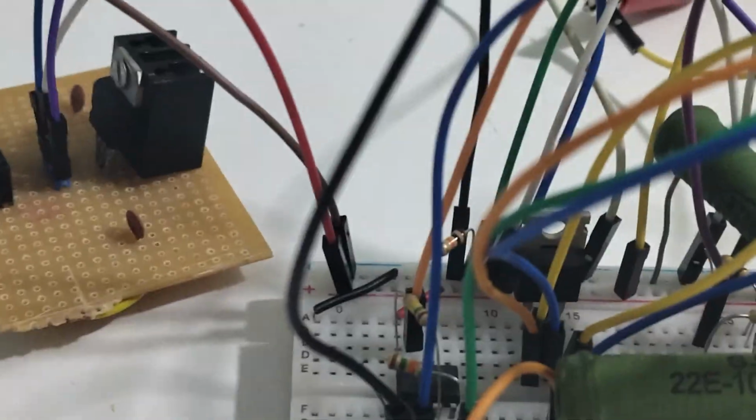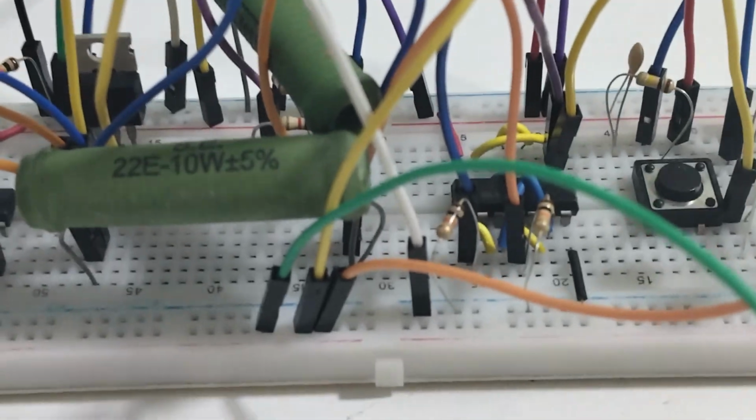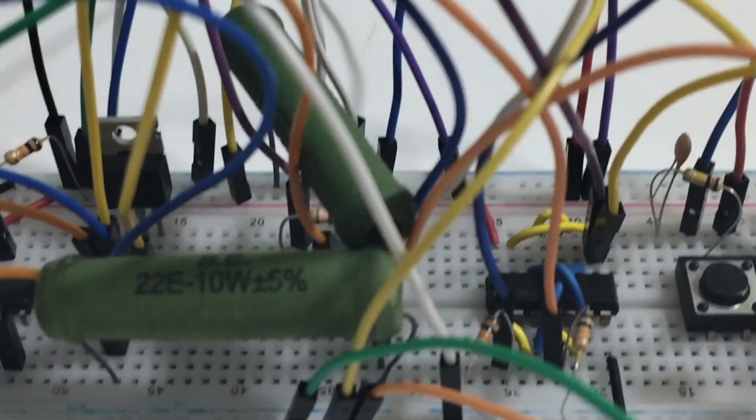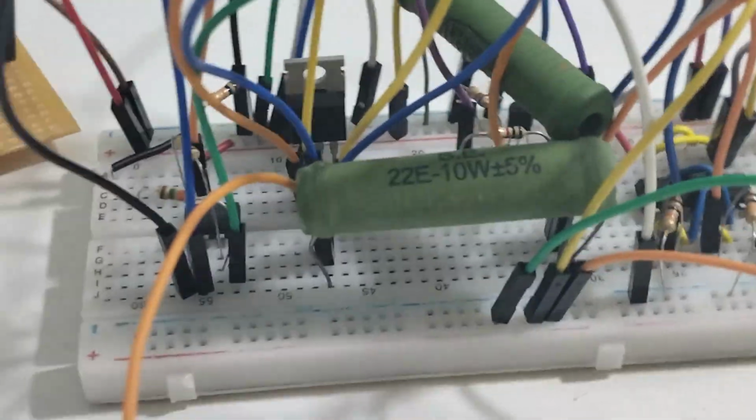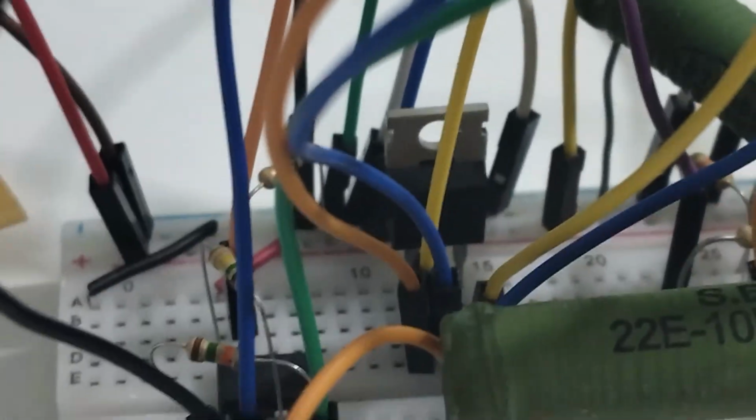It's set to 12 volts, and the comparator has also been given 12 volts, but the gate, you saw it, right? The 74HC works only between 2 and 6 volts, so we can't give it 12 volts. So there's a 7805 regulator there, and there's the P channel MOSFET over there, and the NPN BJT, which I don't think you can see, it's below the 1 ohm.